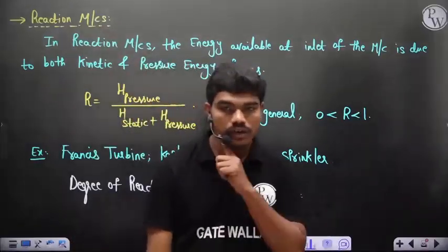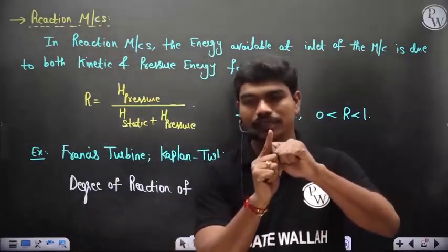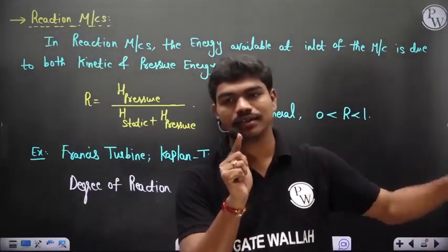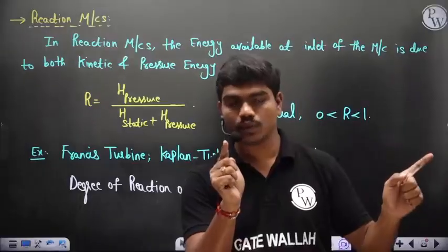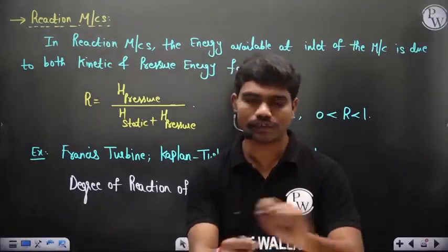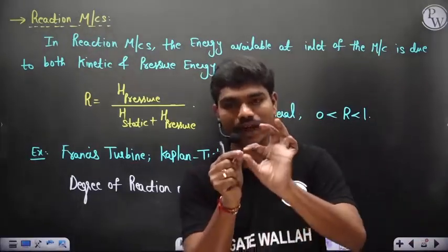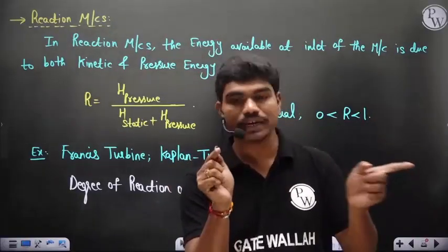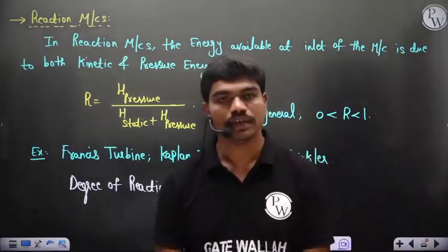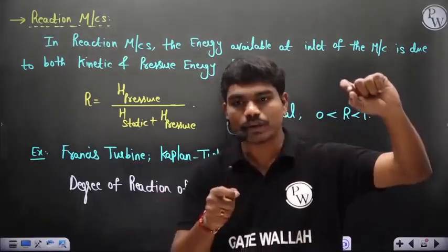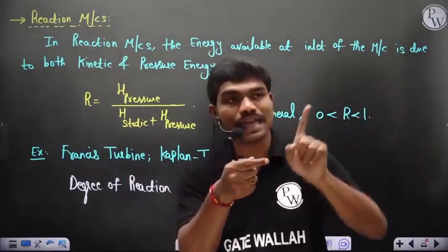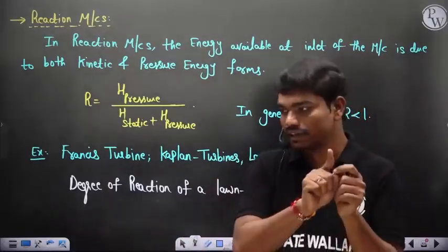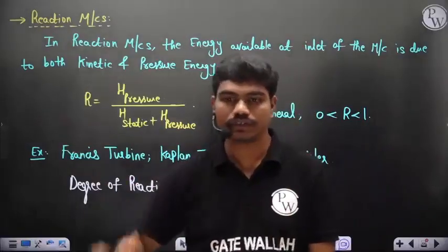Just think. When the fluid is entering this lawn sprinkler, the arm is of uniform cross section. So if the arm is of uniform cross section, then this V1 and V2 are generally the same for a lawn sprinkler, if there is no friction and all, of course. So what happens if you have a uniform passage? In that case, this V1, the fluid inlet velocity into the sprinkler, and the fluid exit velocity from the sprinkler are both the same, right? Like you have taken the case of a plate. In case of a plate, what happens? The entry into the plate control volume and the exit velocity of the fluid chunk is the same, correct? Similarly, the same thing happens in the lawn sprinkler arms. Whatever the velocity with which it enters, the same velocity with which it generally comes out.